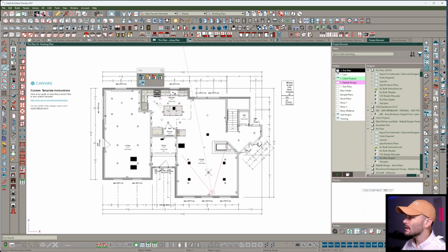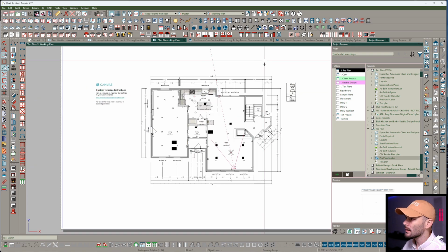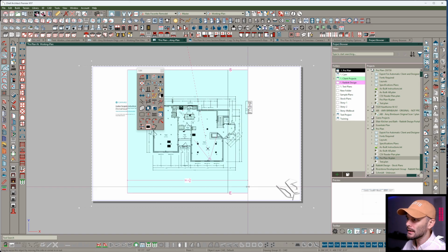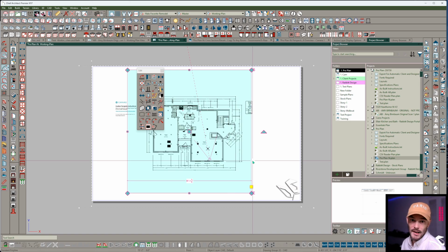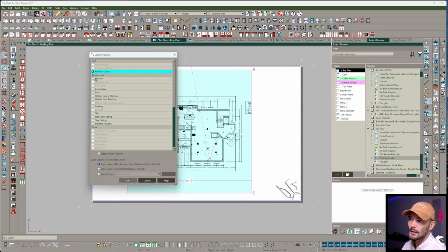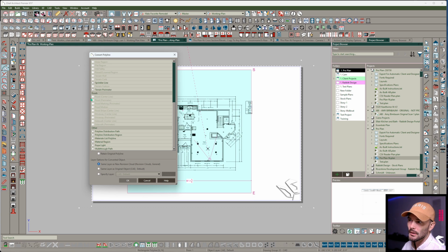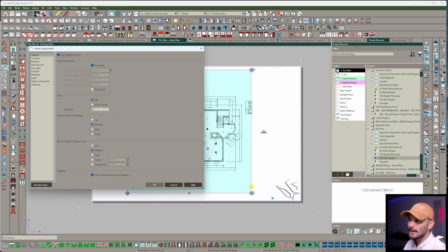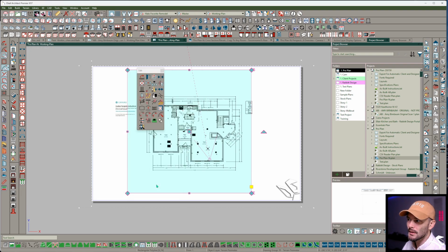So if you see something like this where there's a big polyline drawn in your building here, because you had terrain data before you input some data, what you need to do is just take that polyline and convert it. You're going to convert that to a terrain perimeter, and then that will bring back your terrain in the case that you had a terrain already built. And we don't need to display it in this layer, and we can just press OK.